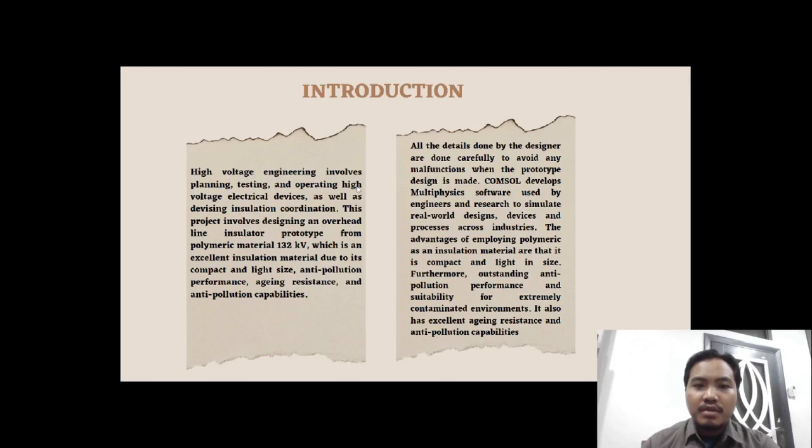High voltage engineering involves planning, testing, and operating high voltage electrical devices, as well as devising insulation coordination. This project involves designing an overhead line insulator prototype from 132 kV polymeric material, which is an excellent insulation material due to its compact and light size, anti-pollution performance, and aging resistance.